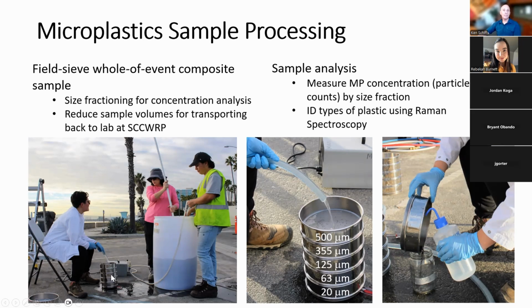So way easier, way faster. It prevents a lot of microplastic settling, or agglomeration with other types of particles. The main thing to know is that if you're going to do microplastic sampling, you have to sample large volumes. It's just that simple. You can't just do 500 mils and say you've got a good representative sample.